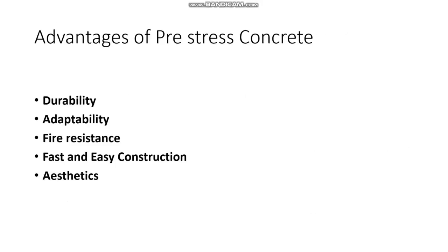Now, our current slide is on advantages of prestress concrete. The first point is durability. Actually, durability is one of the most premium advantages that a prestress concrete structure has. As we know, this technique eliminates weakness of concrete in tension. Such members remain free from cracks. Hence, it can resist the effects of impact, shock, and reversal of stresses more efficiently than a normal RCC structure. Also, they provide reliable long-term performance in extremely harsh conditions that could destroy lesser materials.